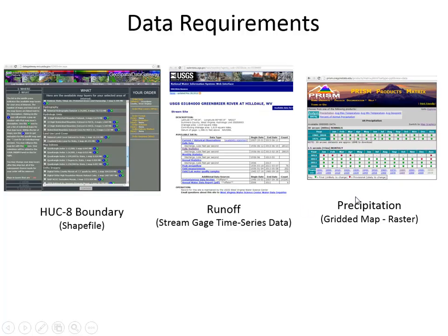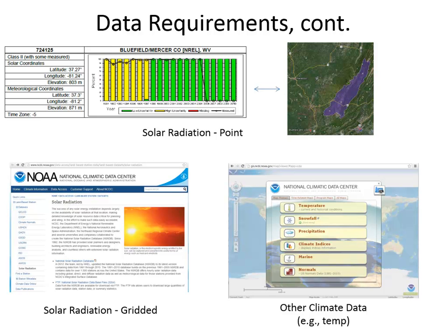And it's gridded precipitation data, because remember I mentioned that in this watershed there's only a couple of rain gauge stations, and so rather than me trying to extrapolate those rain gauge stations, I used what's considered the definitive spatial representation of precipitation data. The other thing, now we're getting into the evaporation a little bit here. The other thing that I needed to do was be able to predict how much evaporation was happening inside of the watershed. And to do that, luckily, in Bluefield, West Virginia, there is a pretty good radiation gauge.